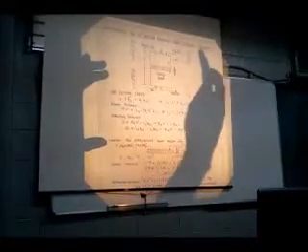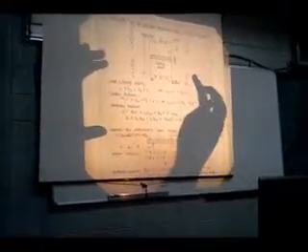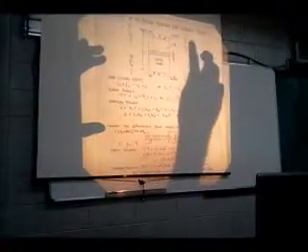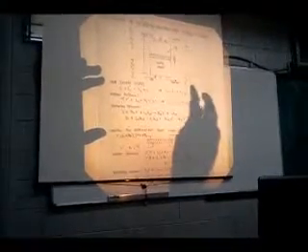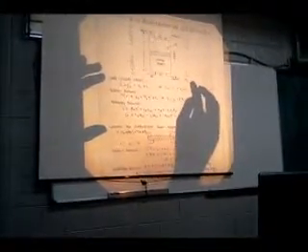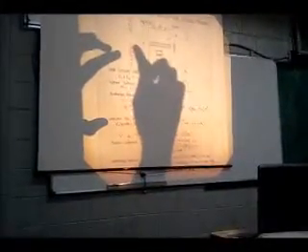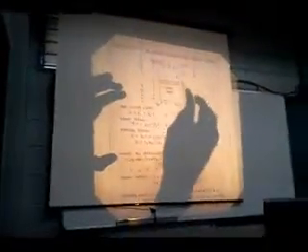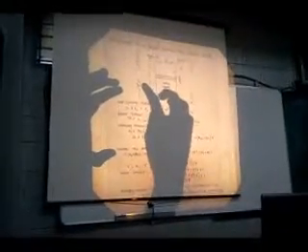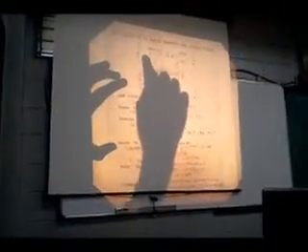And we have L2 and L1, which are the mass flow rates of the water, and TL2 and TL1 are the temperatures of the water, and HL2 and HL1 are the enthalpies of the water. And on the other side, we have Psi1 and Psi2, which are the humidity of the air, and HV1 and HV2 are the enthalpies of the air, and TB1 and TB2 are the temperatures.